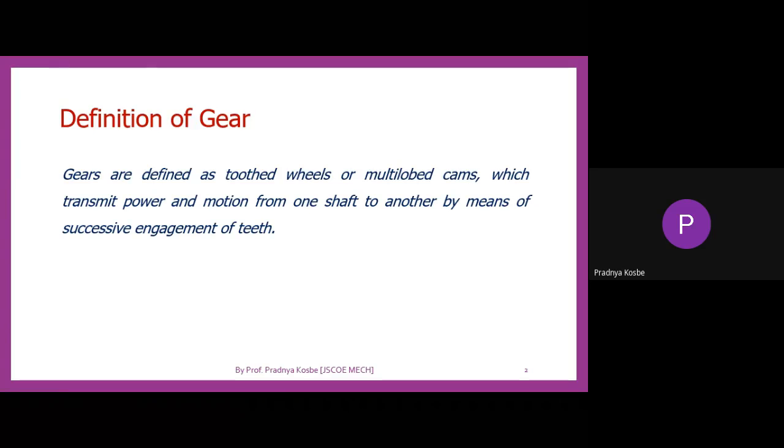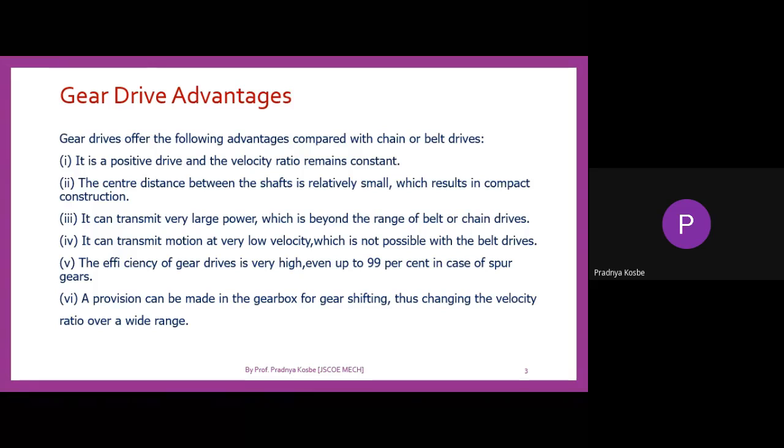There are various types of drives available, like belt and rope drive, chain drive, and gear drive. But mainly belt, rope or chain drives are utilized when the center to center distance is very large. When the distance is small, then gear drives are utilized.